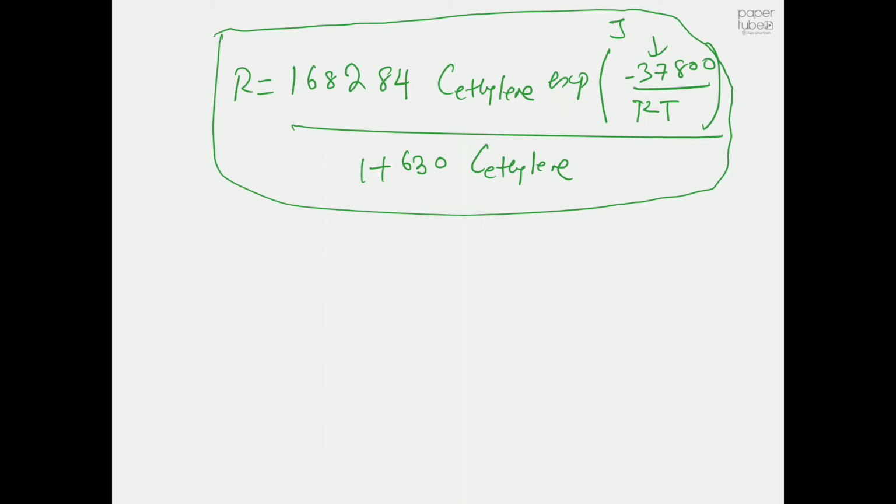For example, direct chlorination follows simple first order kinetics, and oxychlorination, which is a catalytic reaction, follows the Langmuir-Hinshelwood kinetics. Then we need to get those values, the rate constant, and simplify the equation as much as possible.